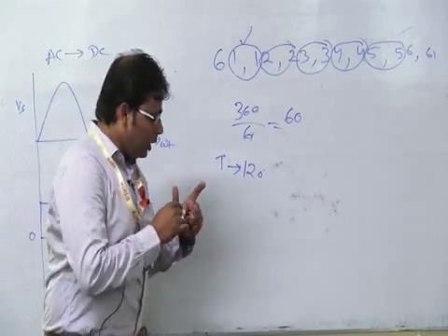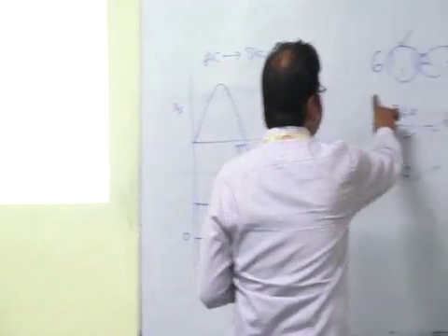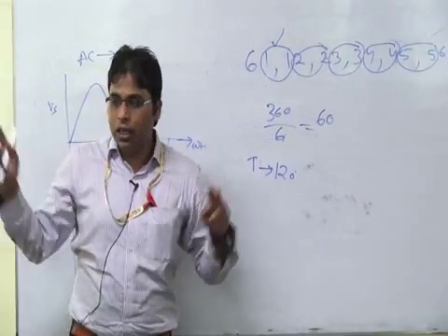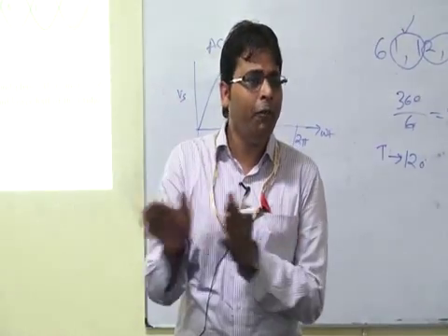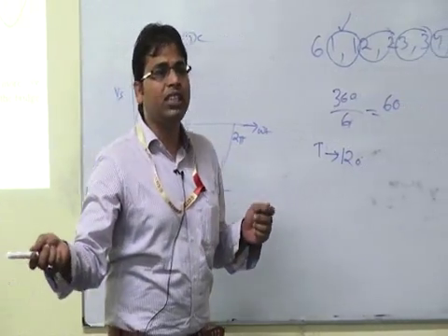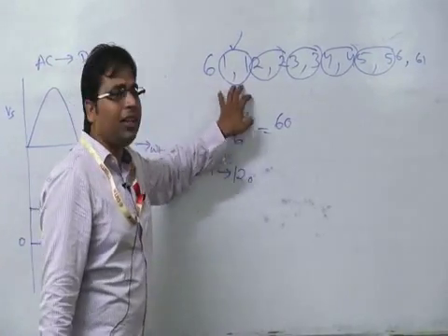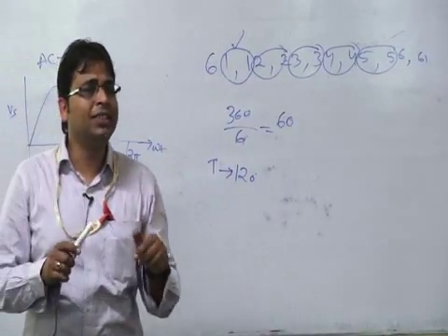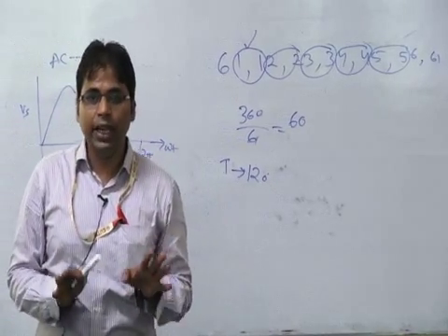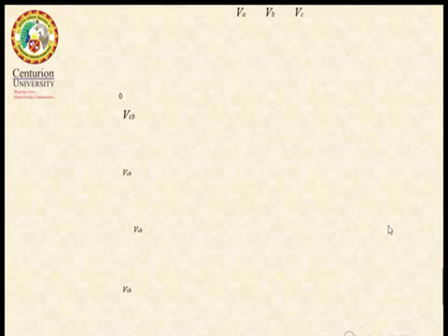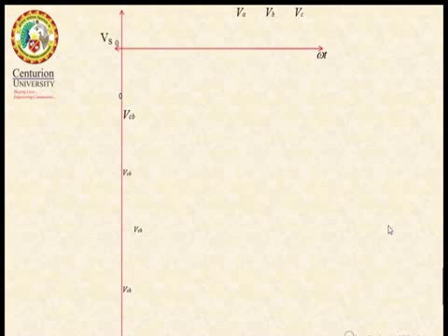Now, this is the conduction sequence. How it came, we have already discussed, during more positive and more negative of phases. Because of the more positive and more negative of the phases, this conduction sequence came. This is nothing but the natural crossover of 3-phase source voltage waveform. Next, let us see the output voltage. During each instant, how the output voltage will be.